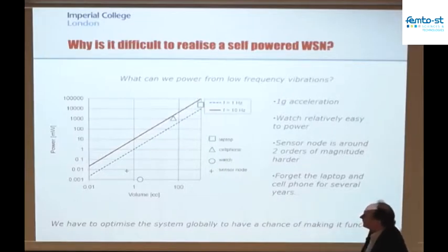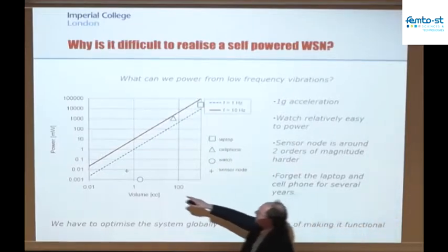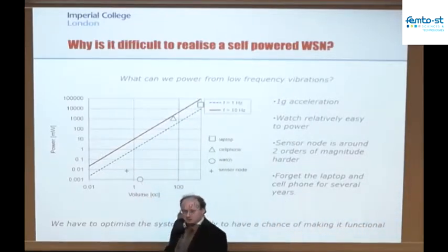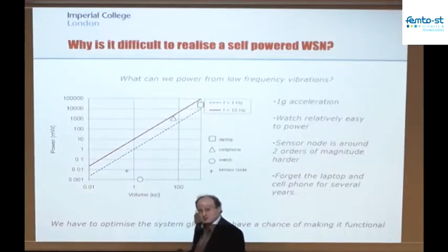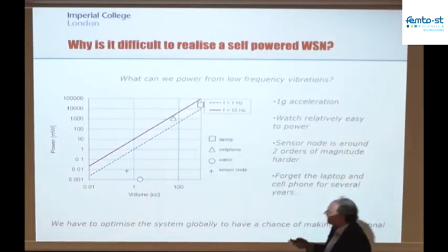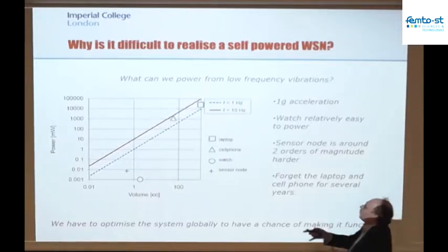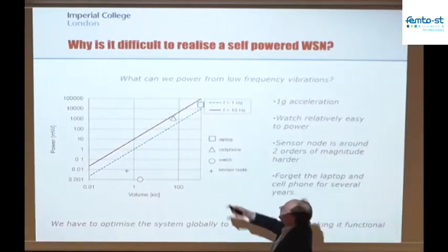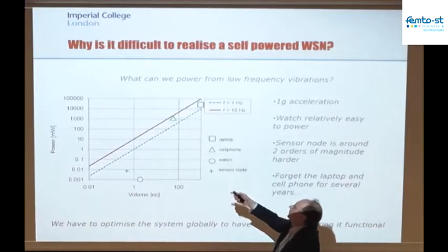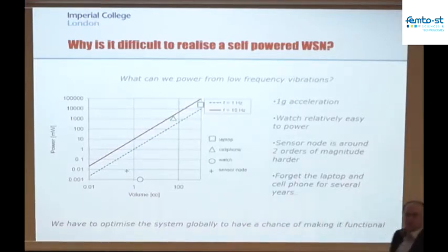The watch, that's not the case. The watch, you can generate way more power than you need in the particular volume for the watch, which is why the watch is such a nice application for energy harvesting. And it's why the laptop, and the same thing for the cell phone, are really not good applications for harvesting, because you would need the entire volume of that device, or more, depending on if it was at 1 Hertz excitation, you'd need even more volume than the device is to turn over to harvester just to power that device.